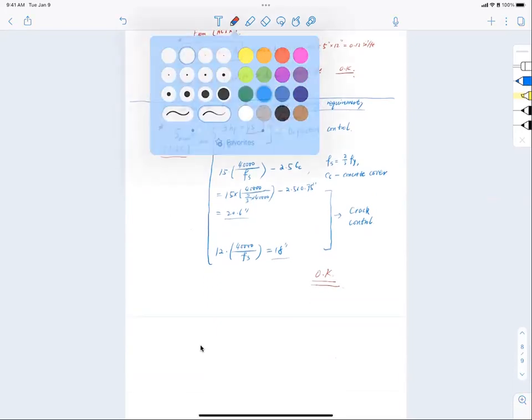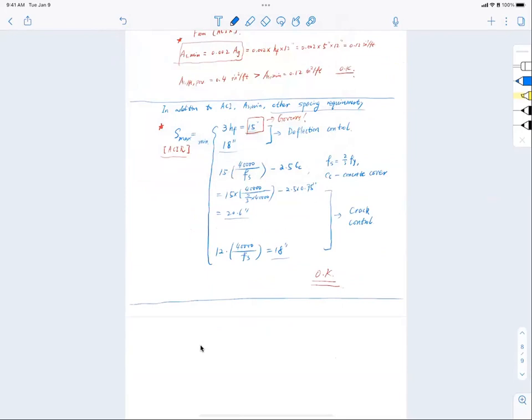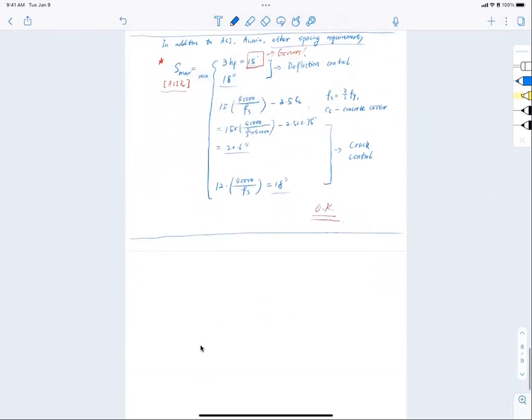Forgive me, I said a little too early that this concludes the longitudinal reinforcement. So I will put here, this concludes longitudinal direction design. Pretty much at this point you have enough bars for your bending direction. That is size number 4 at 6 inches. So it's not too bad.